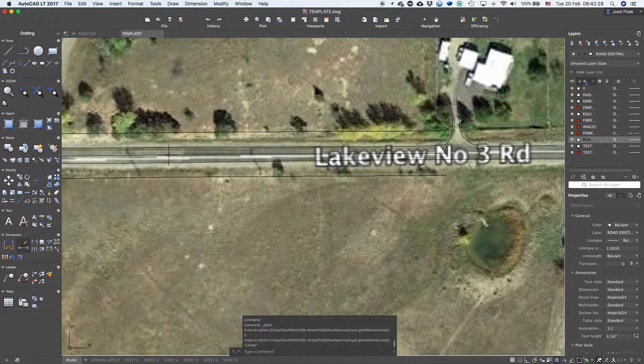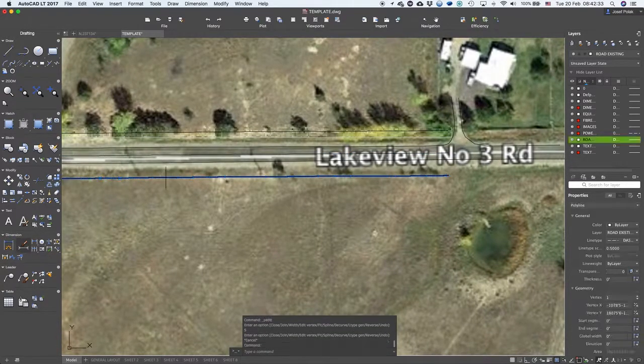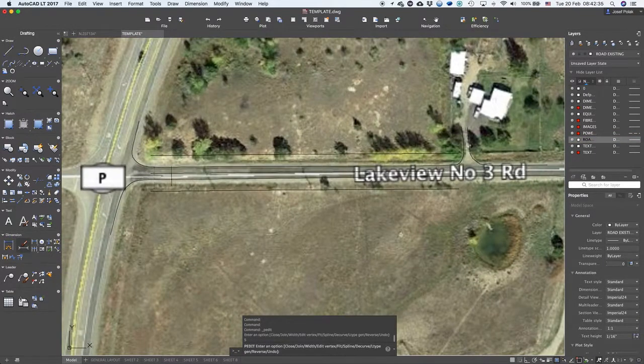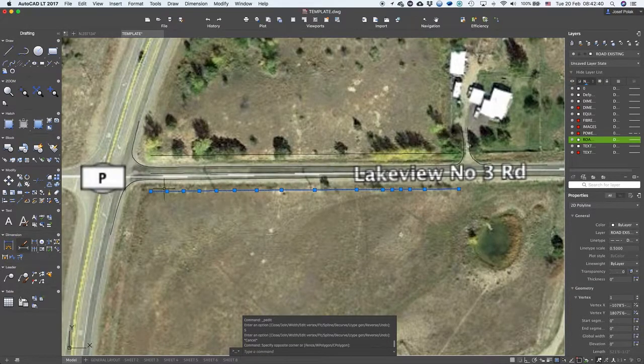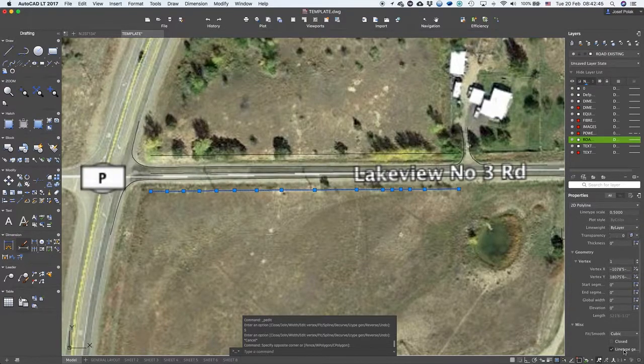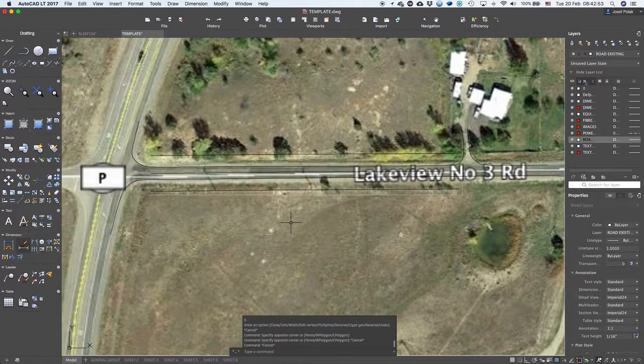So I do it with all the lines, with the center lines, with the right of way lines, with everything. Sometimes when you go to the model space in your paper mode, you won't see the dash line. The problem could be you need to have ticked this. If you have it ticked, it will show, the dash will scale based on your drawing scale in the paper space. So now I have all features drawn.